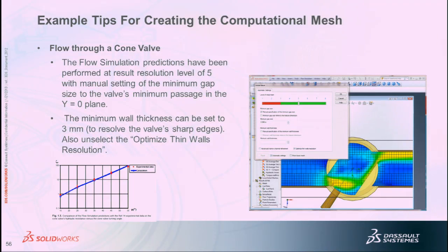All right, and then just to drive home a little bit about the meshing, just to give you an idea, these were some validations, and in fact they're in the technical reference guide that they have. And basically what I want to get across is you first run it at level 3. And if you're happy and satisfied with the results at 3, there's no reason to use control planes and local initial meshes. This is only if you suspect that there's a problem or you compared it to something else and something doesn't look right enough and you need more accuracy.